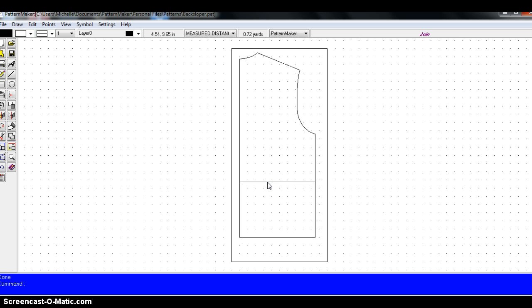Remember that you drew these objects by entering the points or vertices that make them up. Let's use the points on/off function to look at these again. Use your F5 key. A number of X's will appear all over the drawings. These are the locations of the vertices.